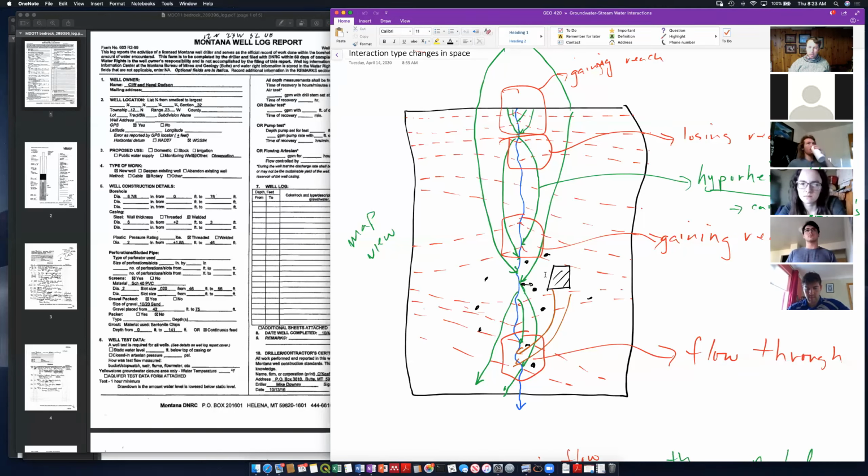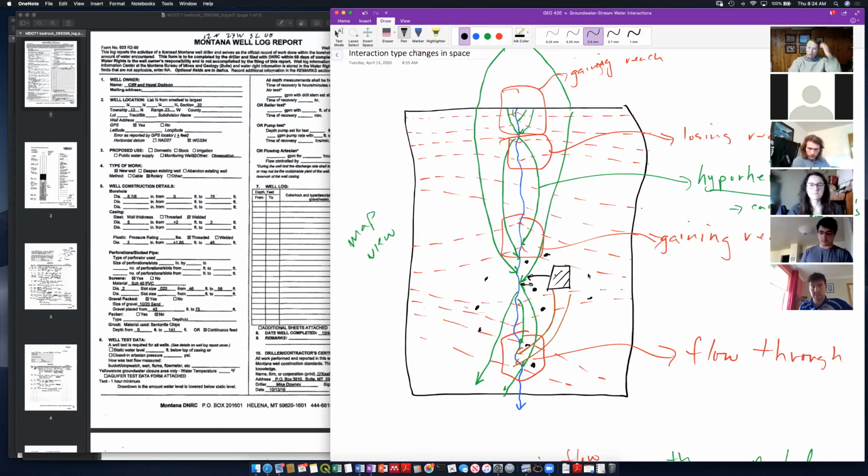So today what we're going to start doing is talking about drilling and in general aquifer characterization. All right. So the things we would need in order to figure out how fast water was moving from our mill to our river, well, we need the head gradient. So we need dh, dl, but we also need hydraulic conductivity. We're going to want to know something about porosity.